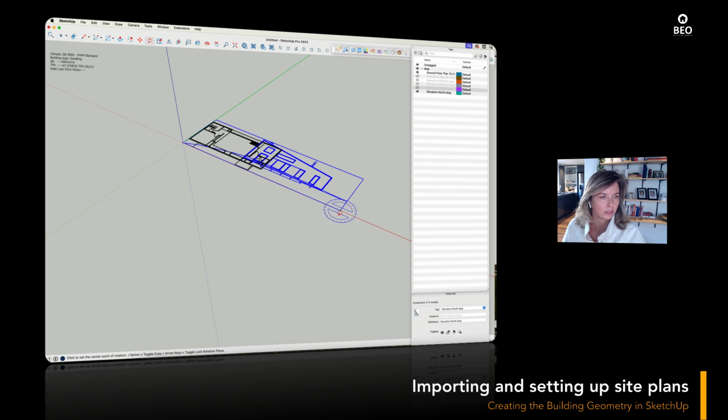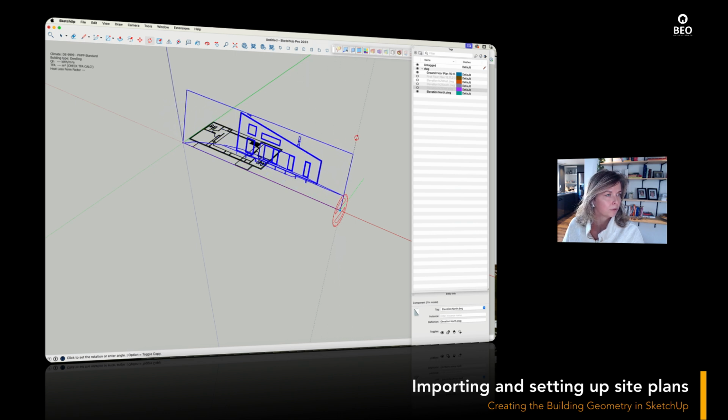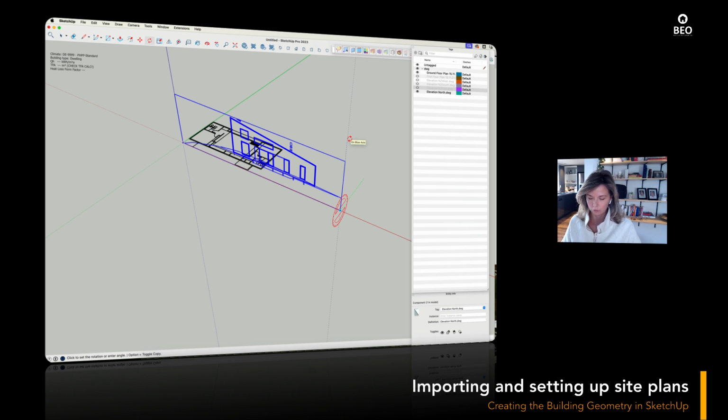First, we're rotating it upwards. So in this case, we need to select the red axis. Select the starting point, and you can select an end point up here on the green axis ideally. And you can manually pull it up, and it typically snaps to the 90-degree axis, but if you're not sure, you just enter 90 and click enter.